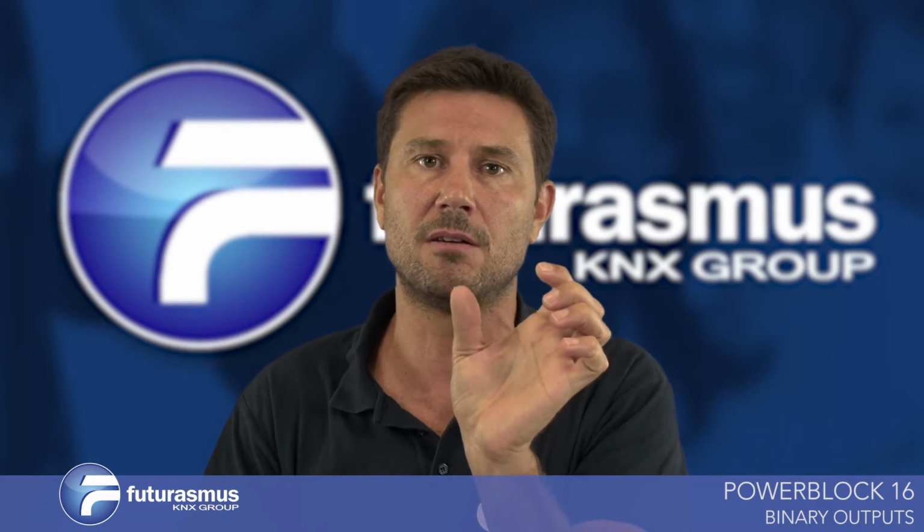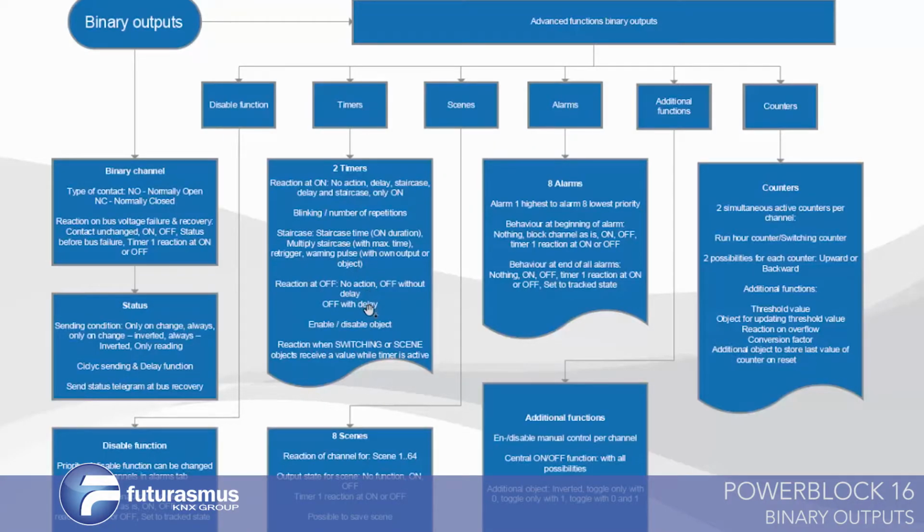So say the staircase time is 1 minute, and you set it not to use the multiplication factor, then it will reset the time to 1 minute. But if it was with the multiplication time, it will reset the time to 5 minutes if you have pressed 5 times in the beginning. So this is a very interesting function. Obviously, you can also decide what should happen if you receive an off during the staircase time. Okay, so these are the timers. As you can see, the timers are very, very complete.